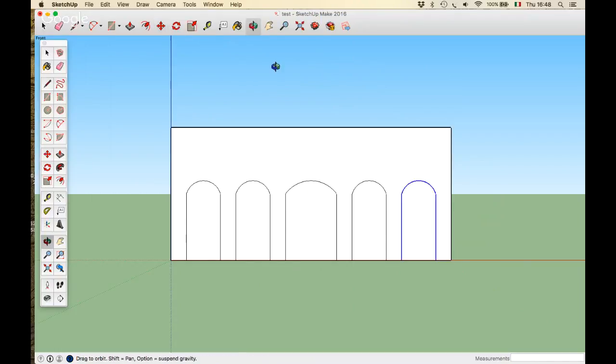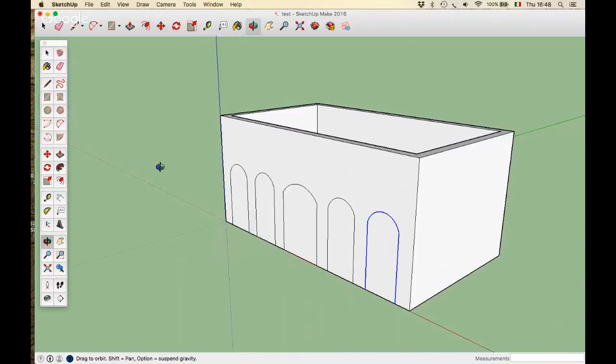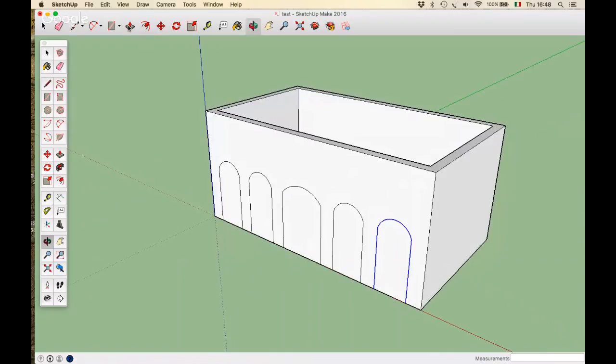So these doors are great, but a little bit useless because we cannot enter. So what we do is we select the pull tool again, and we push them until we open them. And after we do the first one, we just double-click on the others, and SketchUp will reapply the last operation that we did.